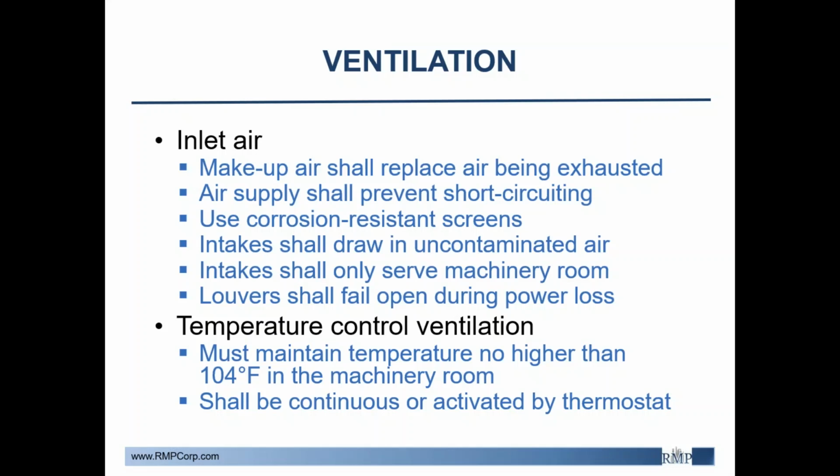As far as temperature control ventilation, IR9 goes further to dictate what a proper temperature would be in a machinery room. Again, building code or local codes may dictate that it should be lower, but 104 degrees Fahrenheit, which I would consider pretty uncomfortable, is the minimum standard, basically no higher than that.